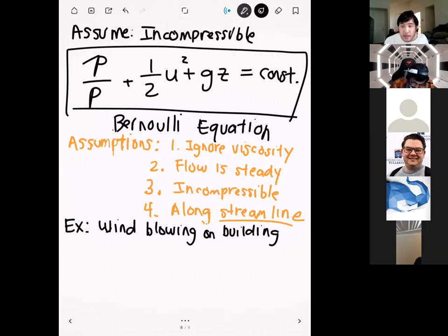So the question is, can I explain compressible and incompressible again real quick? Yeah, definitely. Compressible, based on the word, means that you can take your fluid and compress it into a smaller space, or you can expand it, and the volume is going to change with the exact same amount of mass in the fluid. Imagine you have a balloon full of gas and you compress it into a smaller space. The amount of gas in there is the same, but if you pack it in more, then the density is going to change.